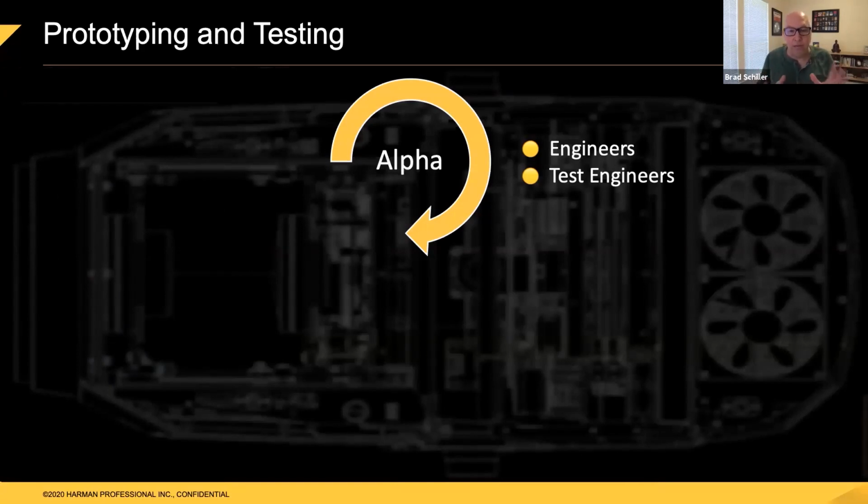and proof of concept almost, because a lot of times once you start putting it all together and you put the light engine in there and you try to check the airflow and you want to make sure the light's coming out through the lenses and where the color mixing is, you might find that all your great planning worked, but if you just move those color flags forward by 0.5 millimeter, it's going to color mix much better.